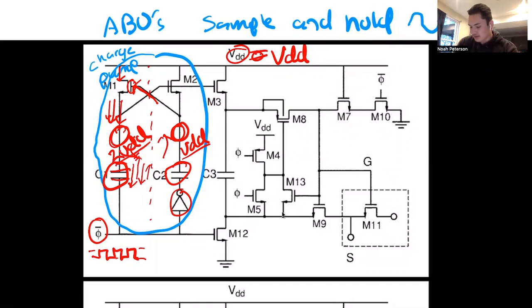Like I said, there's a fair amount going on here, but that's going to allow this 2VDD to come over here, be applied to the gate of this transistor, and allow voltage from this same VDD to be passed into this part of the circuit.